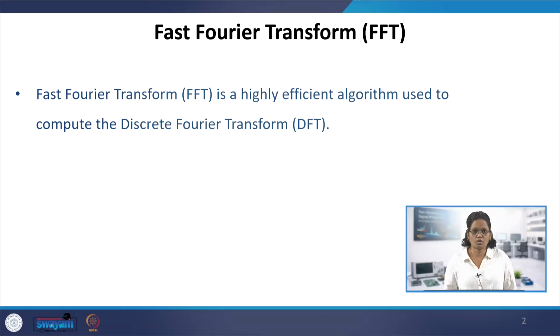So FFT, Fast Fourier Transform, we know this divide and conquer rule of this algorithm, that FFT is highly efficient, which is computationally efficient compared to DFT. We have seen n complex multiplications and n minus 1 complex additions for one k in DFT, whereas for n such k-bin indices, it's going to be n square multiplications and additions will be n into n minus 1.